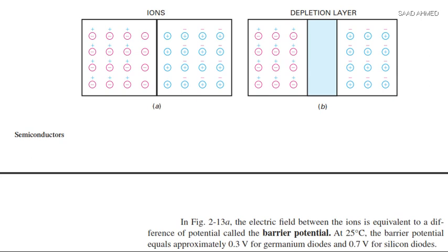We have seen that at this junction, the electrons from the n side cross the boundary and move to the p side, where they occupy the holes present there, and in this process they form ions on both sides. These ions are missing the charge carriers, so they behave as insulators. We discussed that this area is called the depletion region,